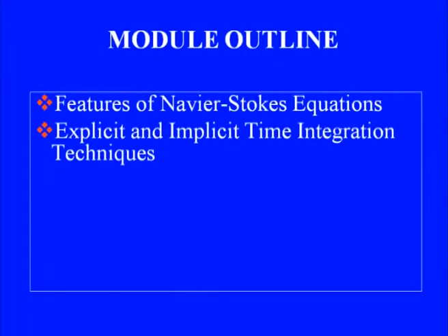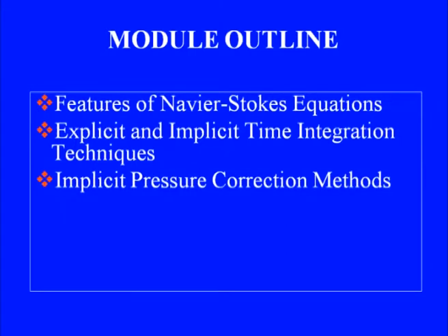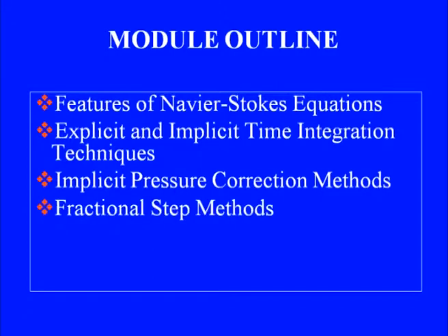And then we will have a look at explicit and implicit time integration techniques as they are applied to the solution of incompressible Navier-Stokes equations. And we would look at implicit pressure correction methods which are popular for the solution of steady state problems, and we will also look at fractional step methods.